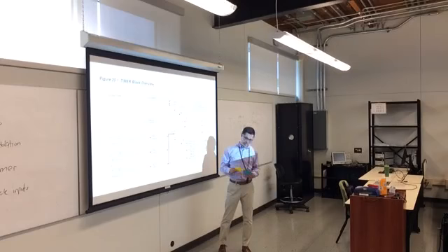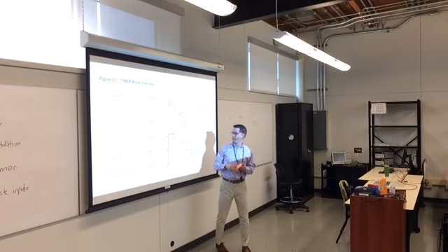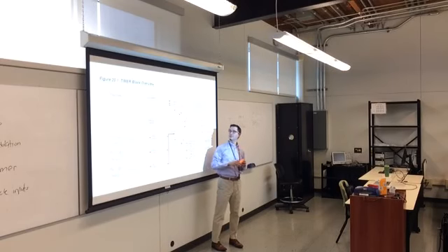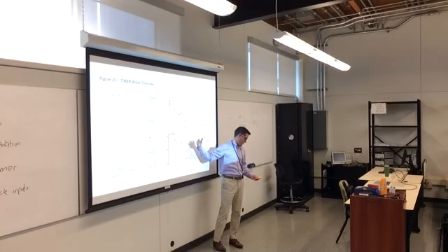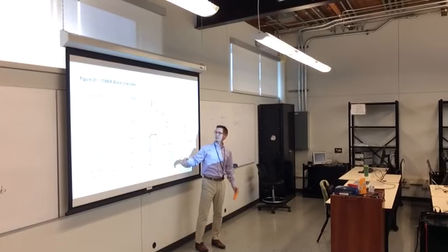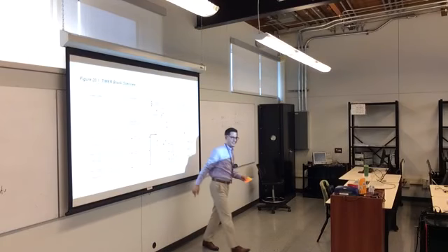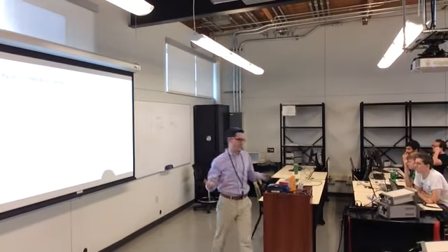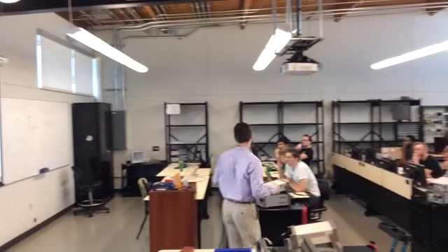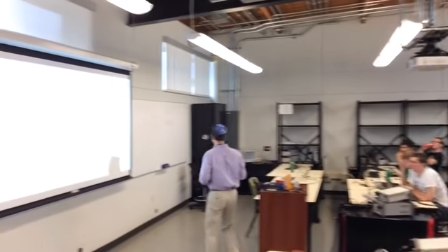What's another one that's important? The timer CCX. Where's this? This? Yep, that's the pin. That's the pin that we can control, we can generate things with. What's the most important one? Like the big box here where all the arrows are going into it. Right, there's a control register that sets the mode, that makes things go up and down. That's one of the other main ones that you need to pay attention to.